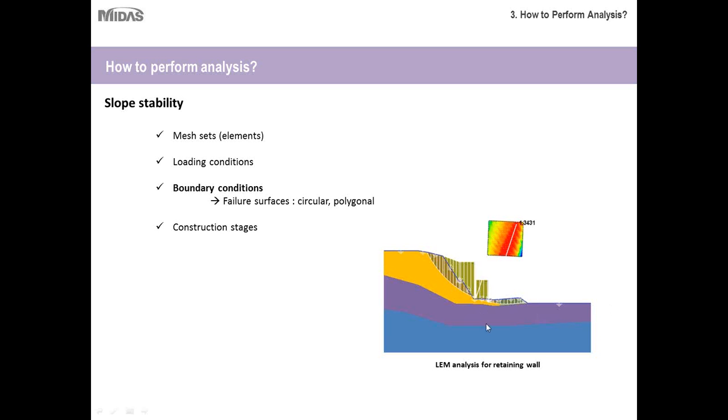In addition to the slope stability analysis, you can also add water level and consider seepage. And with that you can also apply construction stages, and then it will become a coupled or semi-coupled analysis. We covered semi-coupled and coupled analysis in the previous chapter, so I believe you are well aware of that analysis.